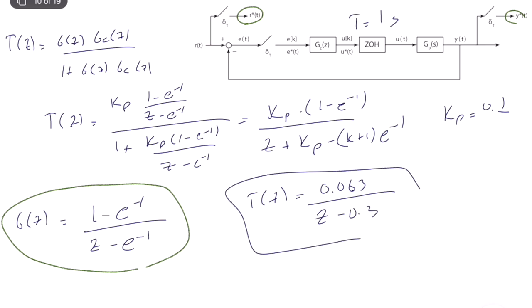So I will later solve different examples, and after the midterm, we will analyze this control system from the perspective of stability and transient performance. But for now, the idea is, given a discrete time or digital control system topology, which has sampling and zero order hold, computing the pulse transfer function from the sampled input to the sampled output, which looks like this for a general K. And for a specific K, you can compute that.